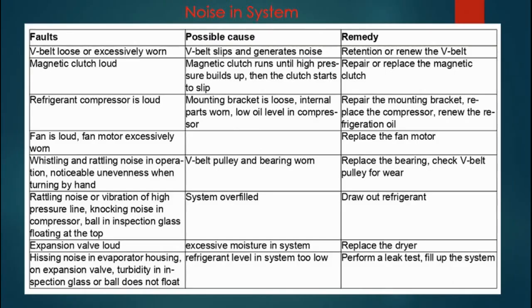So these are some other faults which we can find, noise in the systems. The first fault is the V-belt loose or excessively worn. Its possible effect is that the V-belt slips and generates noise. Its remedy is retension or renew the belt.